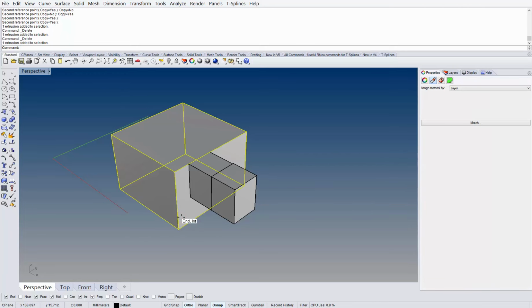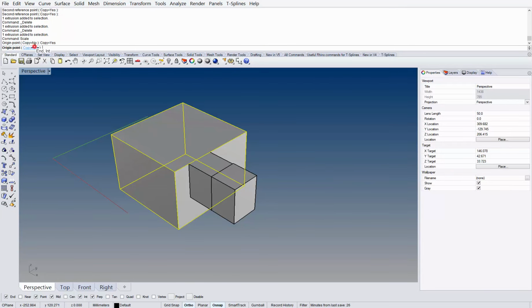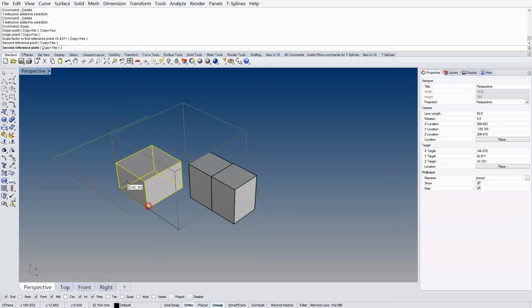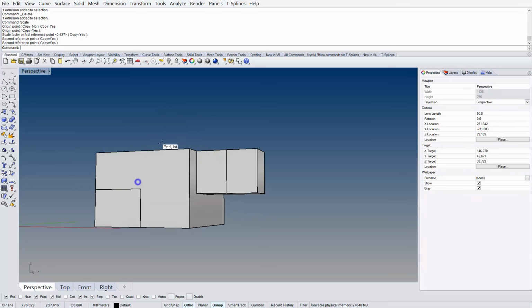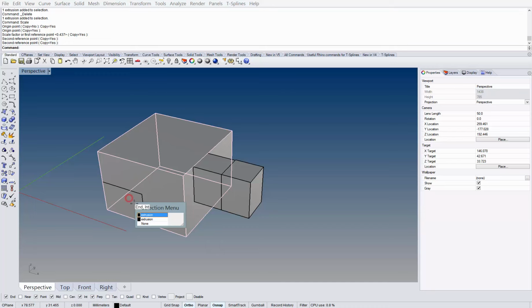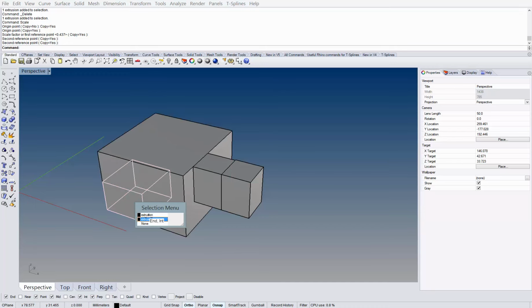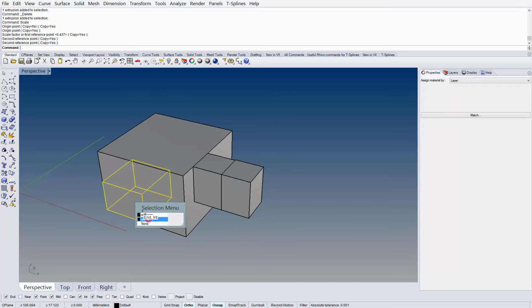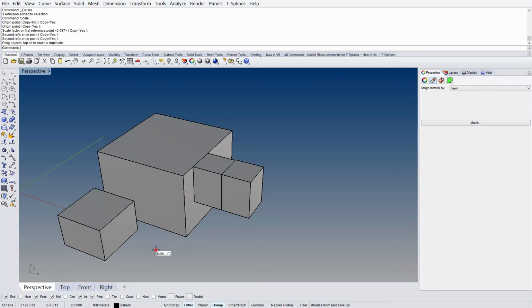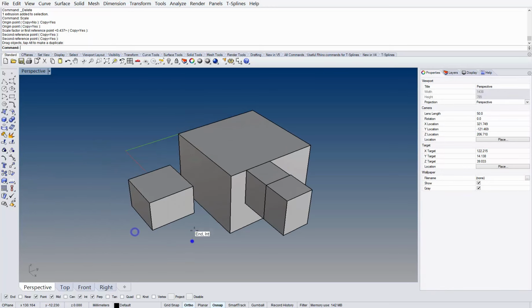So if I was going to scale it, I could select the object, scale, copy yes, and this time I'm going to scale it down like this. It made another smaller object in that one, and we can select it, and it's going to ask me which one I'm trying to select, and I can move and drag and rotate it out like that, and drag it out so you can see it.